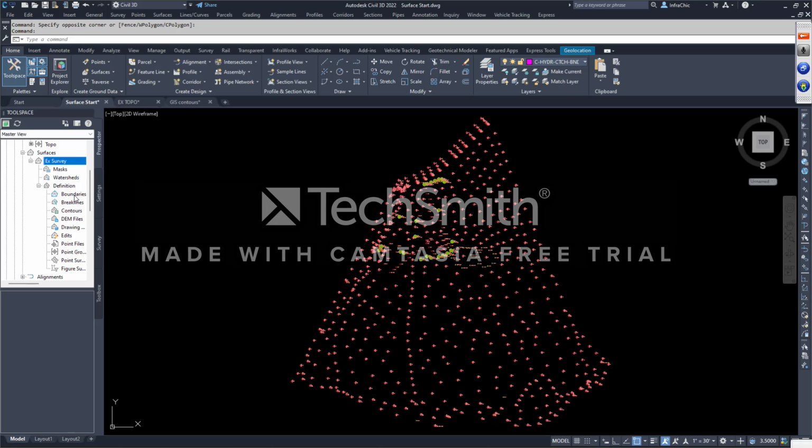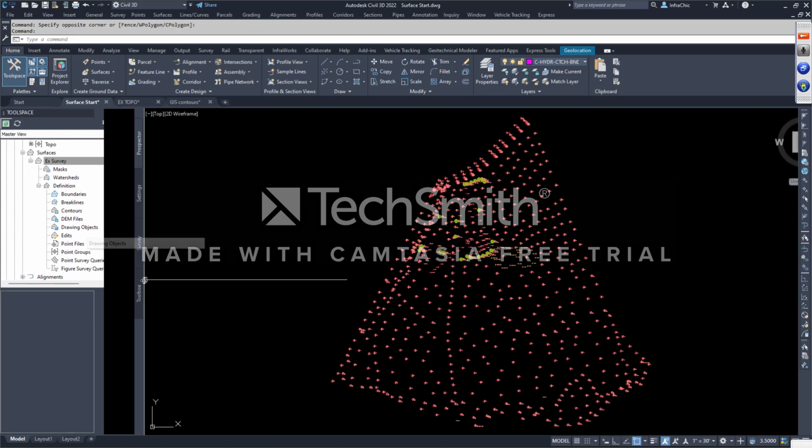A surface can have boundaries, break lines, contours, polyline contours, mind you, elevated, not set to 0. So that means when you select a polyline, it has an elevation on it in the properties dialog box. DEM file, you can go get one. They're XYZ files basically. They're big. I have a surface that's like that. It's huge.